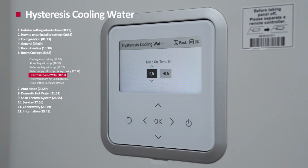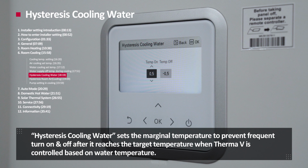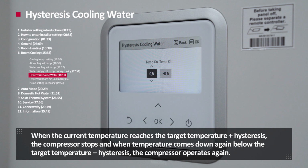Hysteresis cooling water. Hysteresis cooling water sets the marginal temperature to prevent frequent turn on and off after it reaches the target temperature when Therma V is controlled based on the water temperature. When the current temperature reaches the target temperature plus hysteresis, the compressor stops. And when temperature comes down again below the target temperature minus hysteresis, the compressor operates again.